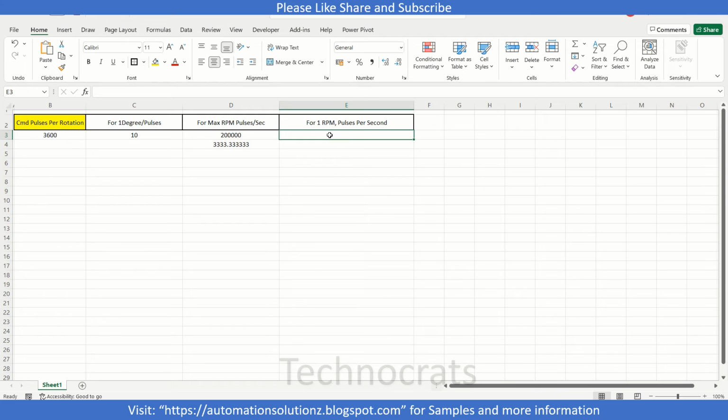Now for 1 RPM, how many pulses do we have? That is the maximum pulse divided by this, and we get 60 pulses per second if we want to rotate the motor at 1 RPM. So for 1000 RPM, that will be this value multiplied by 1000.